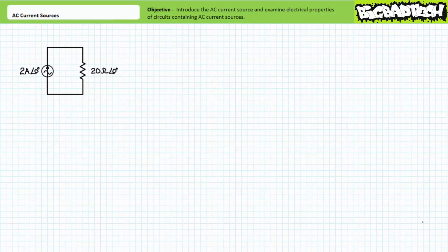Given sinusoidal AC current continually changes not only in magnitude, but also polarity, the arrow in the schematic symbol is of dubious utility when considered in isolation. However, polarity is important when a circuit includes more than one source. The arrow simply implies that at the start of the analysis, current happens to be traveling in the direction of the arrow. The same thing can be said about the polarity markers for an AC voltage source.